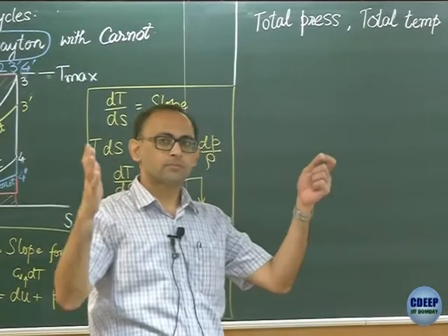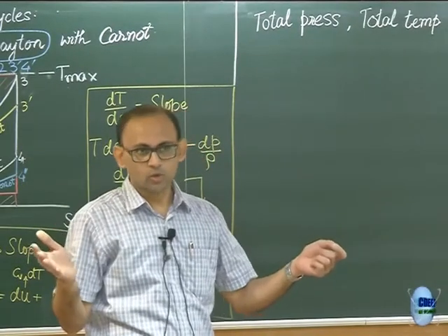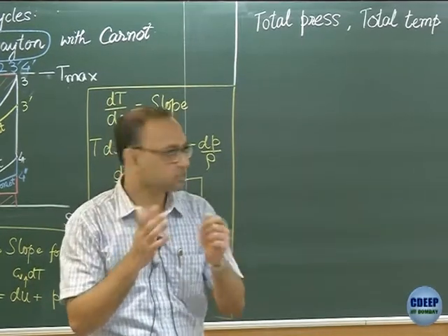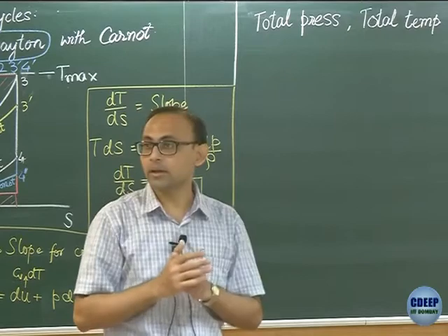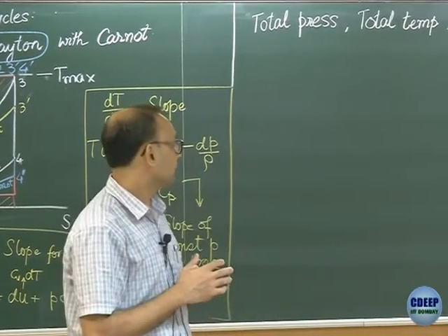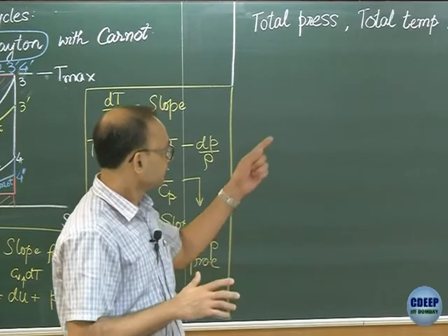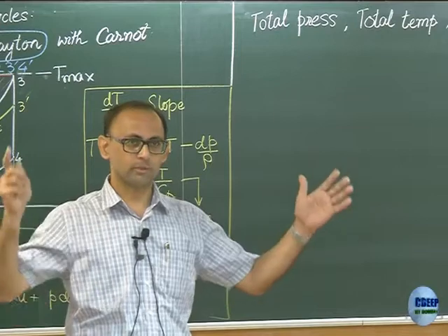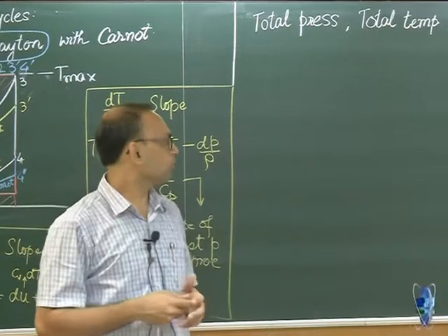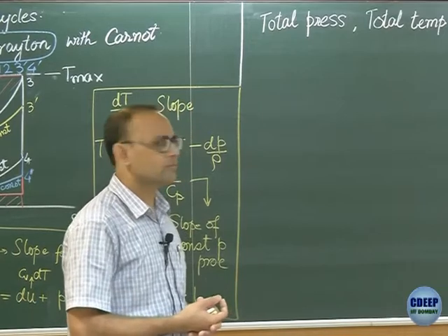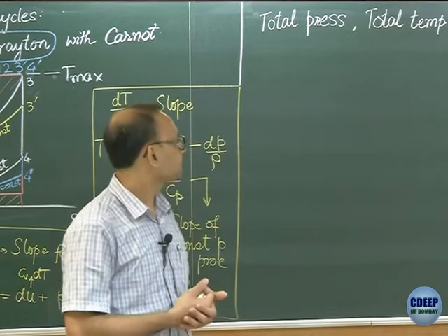We have a flow through device which can be the entire engine, or part of the engine, let's say a combustor or a compressor or a turbine, whatever it is, or for that matter a nozzle or an intake duct. This equation says mass flow rate times the change in total enthalpy from inlet to outlet, and for the time being we are assuming only one inlet, one outlet. Works out fairly well for most of the aircraft engine analysis.